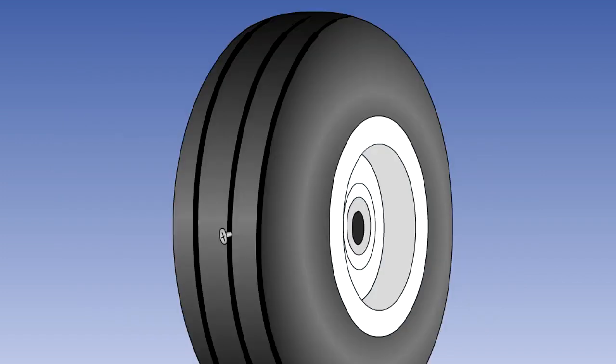Foreign bodies, such as pieces of metal or glass or stones embedded in the tyre, must be removed, and the cuts probed with a blunt tool by a technician to ascertain their depth. Repair or renewal of the tyre is governed by the extent of the damage. If you are in any doubt about the serviceability of a tyre, have it checked before flight by a suitably qualified technician.